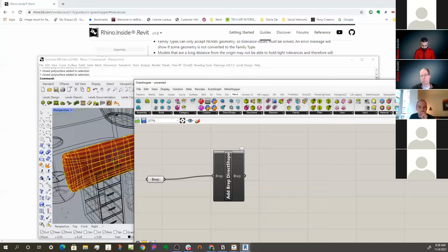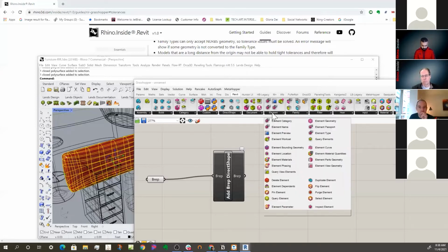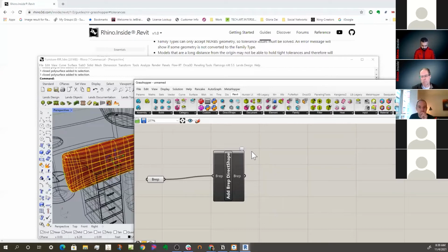If you found that problem, you can drag and drop another component that allows you to audit that geometry and would give you more information about what edge is out of tolerance, what BREP is wrong, or something more specific, instead of adding this success or index output in all the components that are converting.